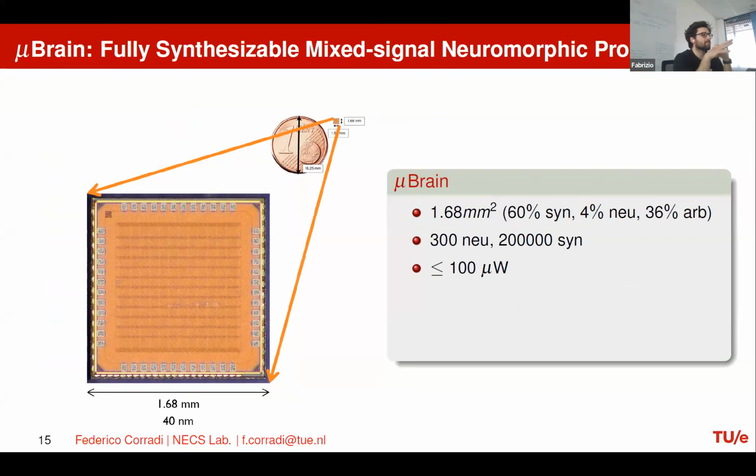Yeah, I understood that basically it's a register-based in-memory computing architecture, if one wants to look at it from an external perspective. I would not say in-memory computing architecture, because the memory is distributed, and it's close to where it needs to be. But we're really using the memory here just as a synaptic weight. So it's just the lookup that you do at the neuron. It's not really anything fancy, I would say. It's really a memory cell, right? Not a tunable device. No, it's a flip-flop per bit, and you can program it.